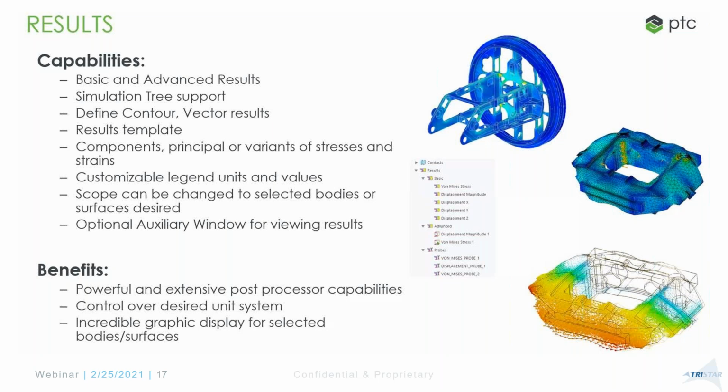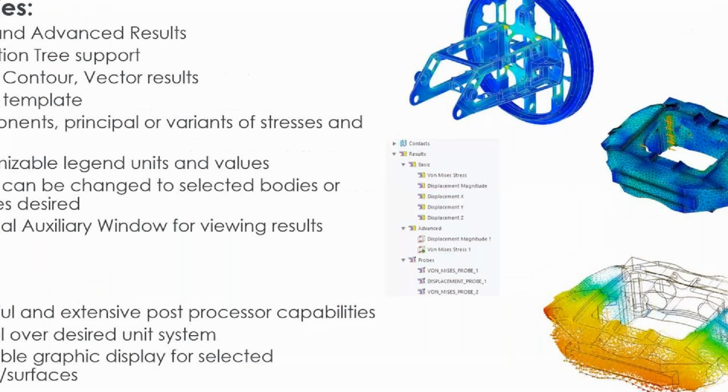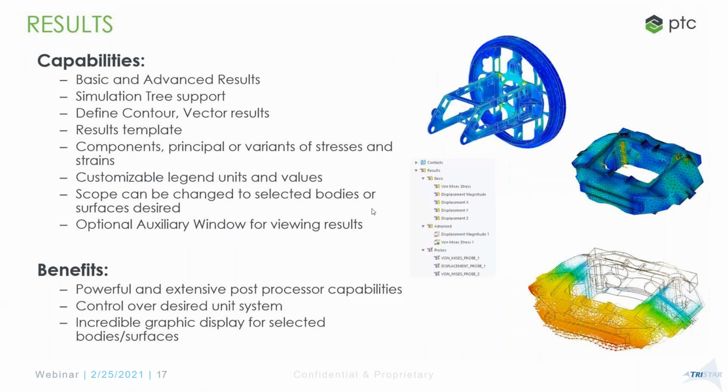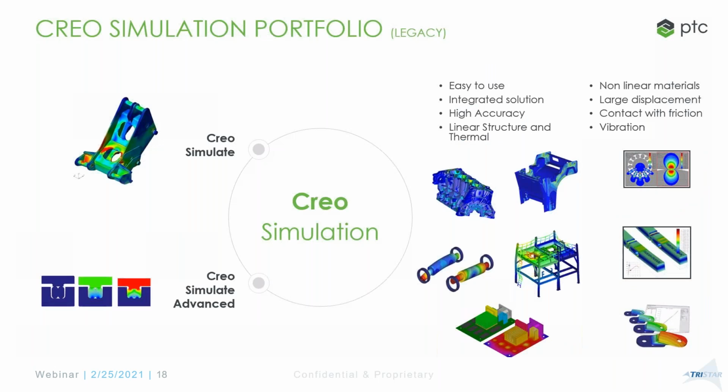Save the results. You're able to export everything as an XBR file, all your setup and everything, including your results, and then you can reuse it later on during a design review meeting, or maybe even create templates. As a company, you may do certain analyses on certain products very regularly, and I may want to just save out my templates as an XML file, so that others in the company who may be new could reuse these templates for future use. Now, when they work on their analysis, all they do is use a template, so it quickly gets these different results that I typically plot out when I'm running a structural or a thermal or a modal analysis. Okay, so just before I do a demonstration of some of the